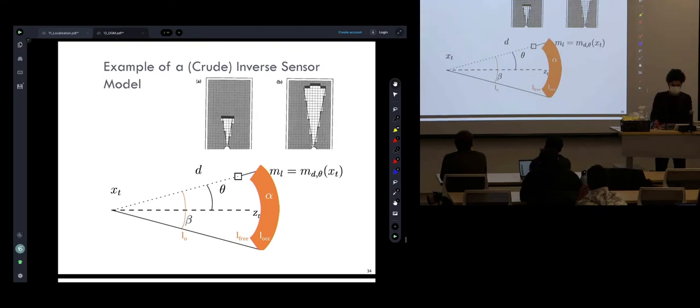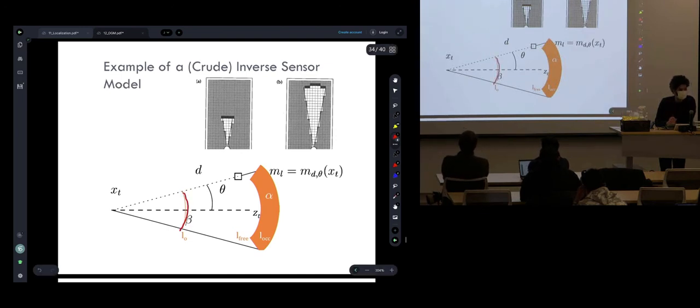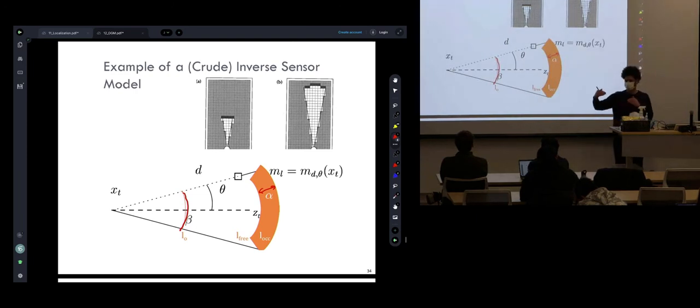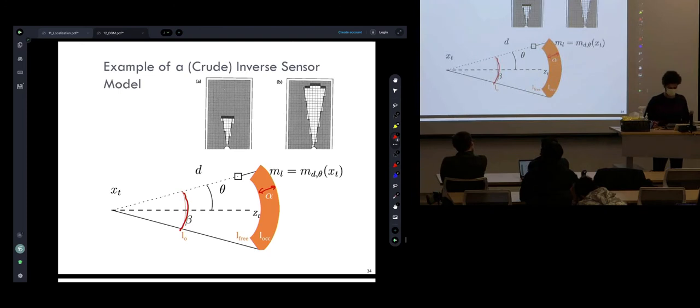So you might give them some names so we can implement an algorithm. The thickness that we're going to consider for the beam is parameterized by this beta angle. We turn a single line into something like a cone. The alpha is this cylindrical thickness of the observed obstacle area. Now, in reality, this is a point. When we model it, this is an exaggerated version of how to model that point, so that a single beam can cover a fair part of the map.